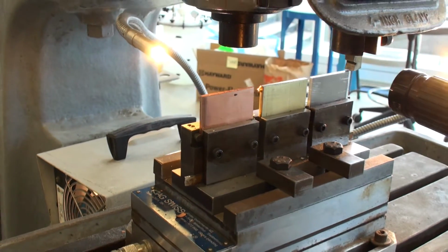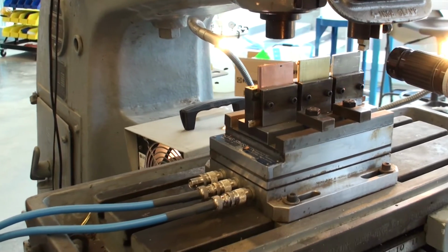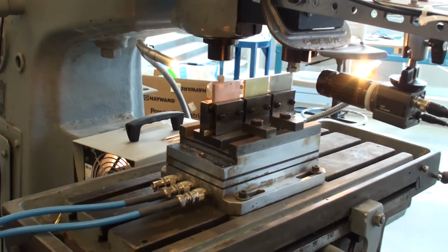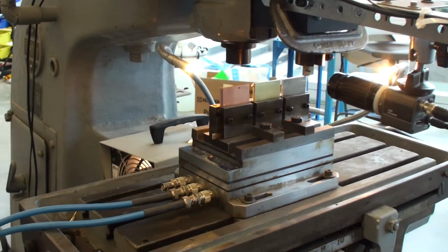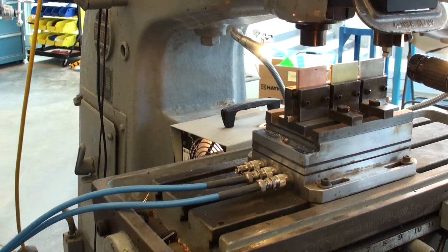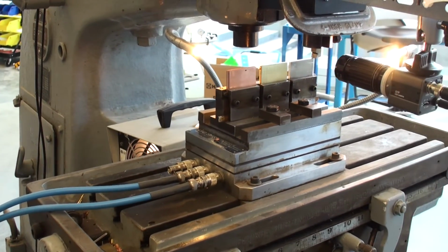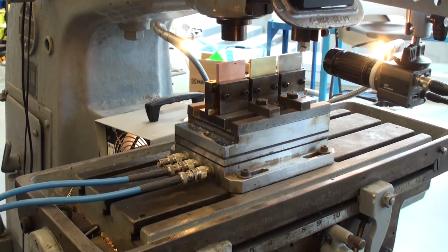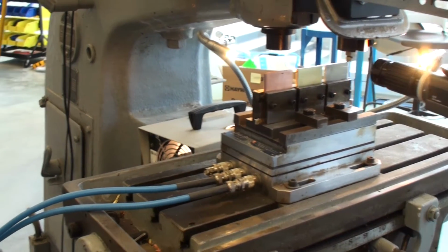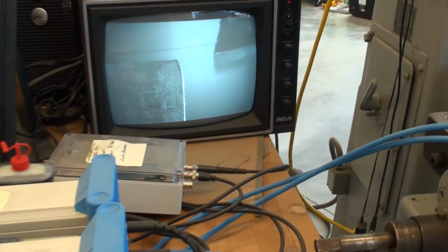In this lab, we're going to be varying the speed at which we're feeding, so the table feed is going to be varied, and we're going to stay with a consistent depth of cut as we go across our 3 different materials. As we do this, we're going to be measuring both the horizontal and the vertical force, and then once it's produced a chip off of each material, we're going to measure that chip thickness.